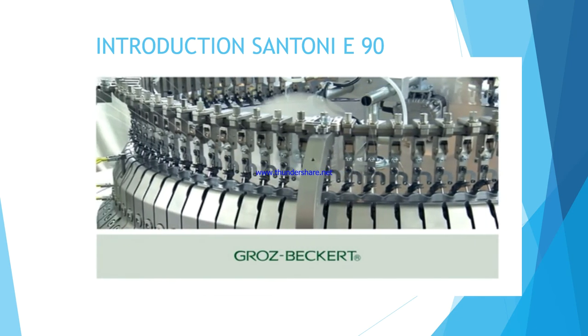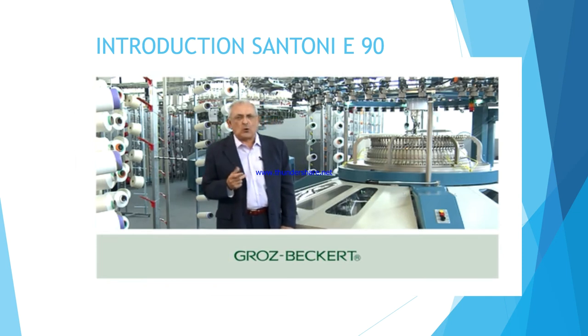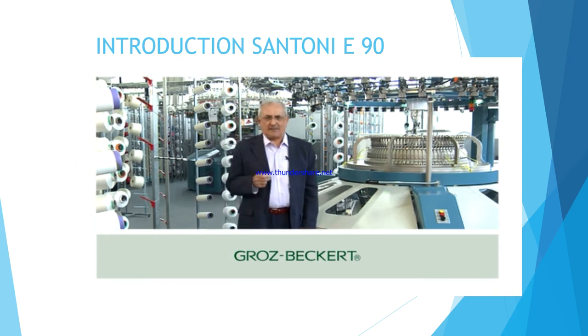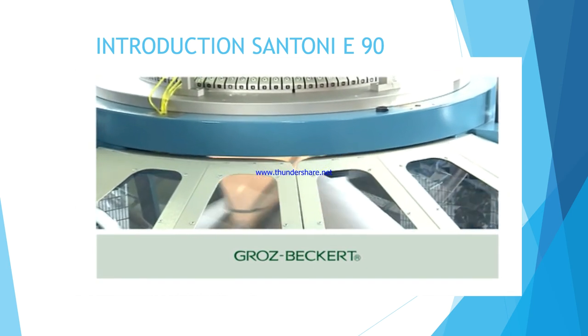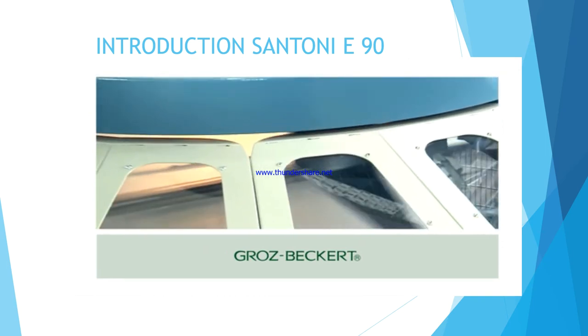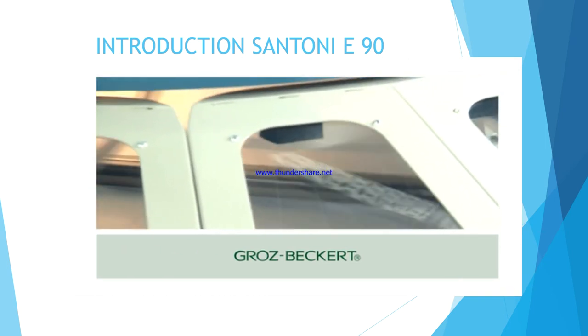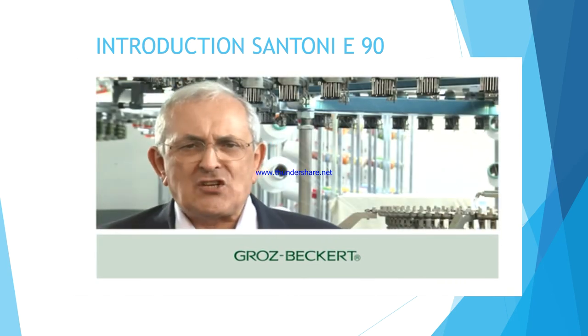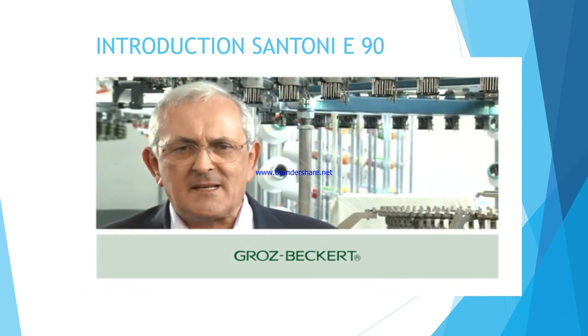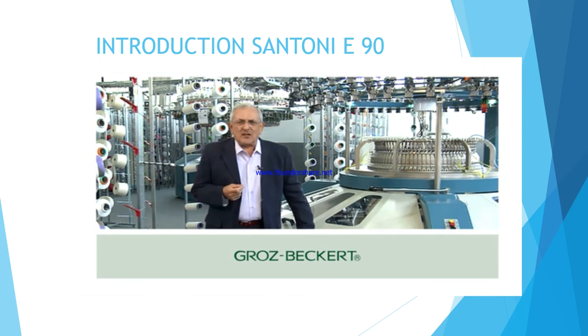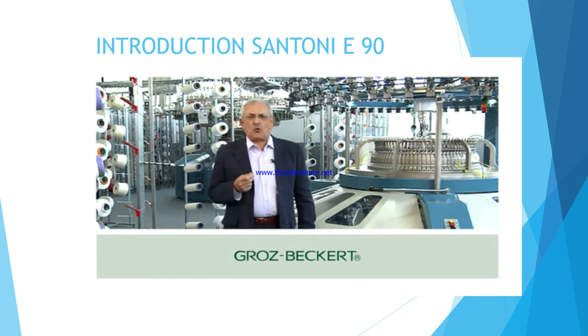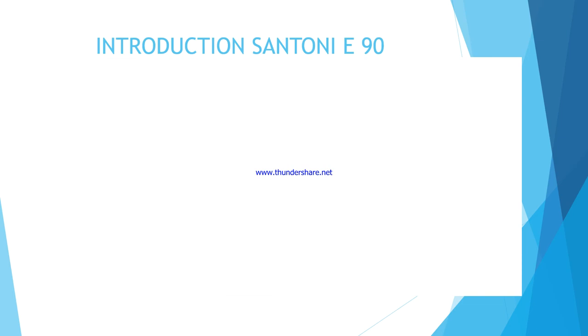This system, patented by Santoni, offers clear advantages in terms of energy consumption and heating of the textile head. In this gauge, the total friction force applied to the needles is approximately 40% lower than that of a machine with a traditional cylinder. The cooperation between Santoni and the Groz-Beckert Technology and Development Center enabled us to realize this ambitious technological development. The excellent results are making us consider new projects together with the Groz-Beckert Technology and Development Center.